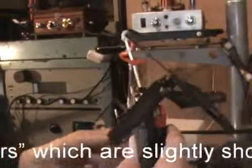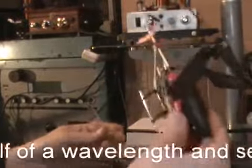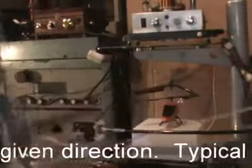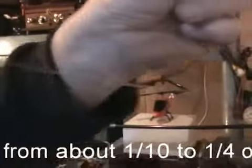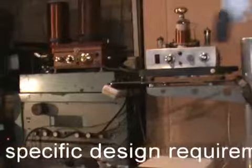I have removed and replaced the onboard battery with this Yagi antenna. The dipole driven pair has a SMD Schottky diode between them, just as in the previous demonstration. I also add a SMD voltage regulator and small inductors and capacitors to tune the received energy to be compatible with this helicopter's original battery operated control circuitry.